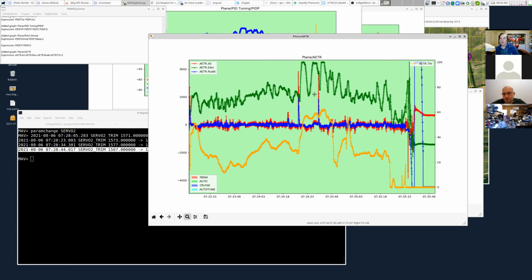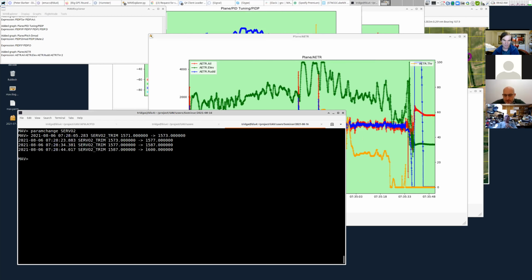He needs to check. The way I would check it is after you land it, you pop it into manual mode and you see where the surface is, right? I would expect it to be a little bit up because the servo auto trim has been trying its best to compensate. But if in fact it's down when he lands and pops it into manual with no stick inputs, then that means there's indeed something wrong with the linkage, or the servo, or the CG, or the gears.